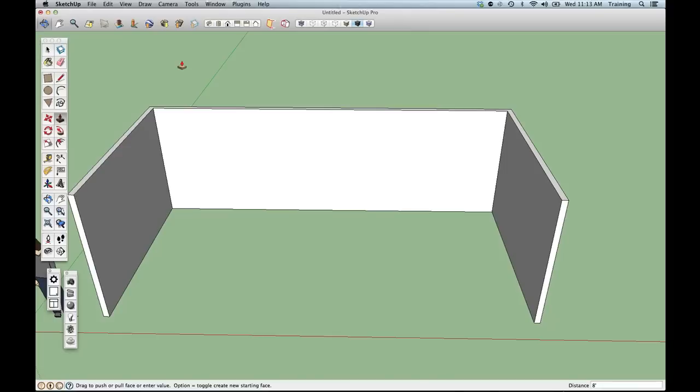I'm going to pause for 1 second and just talk about inputting measurements and answer a couple questions here. So I've been putting in imperial measurements the entire time here, and that's what my default is set at. The way SketchUp works when you put in any dimension is that you can give it a dimension in any format that you want. So for example, if I'm drawing a line and I wanted a 12-foot line, I was able to type in 12 feet and hit enter. I could type in a 3M line, which would be a 3-meter line, which might be something you guys are a little more familiar with. Since SketchUp draws everything in full scale, it doesn't matter what dimension format you put in, as long as you're explicit about what you put in.